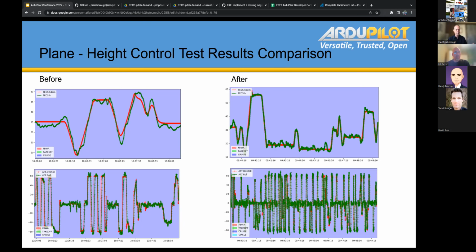And then it comes down to prioritization. If you're clipping on pitch rate because you're hitting your load factor limit, you obviously can't achieve that combination of horizontal and vertical, then the question is, what do you do? And usually you would prioritize height.